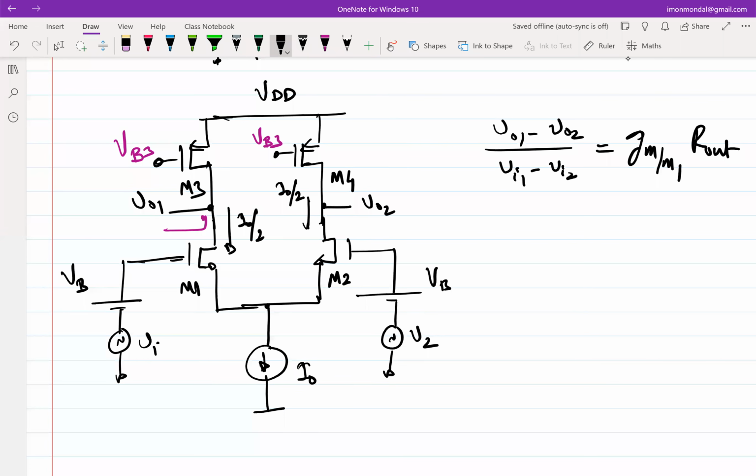I cannot go crazy and say I will have 1 mega ohm resistance. The moment you have 1 mega ohm and 1 milliamp current flowing through it, the voltage drop across it is 1 kilovolt, which is not sustainable. So for a finite VDD, you can only have a smaller value of resistance as a load.